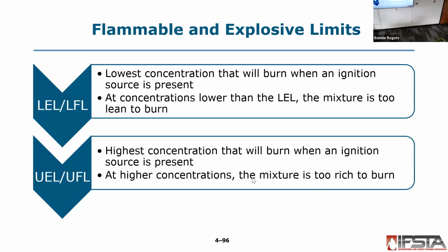All right, so we have our LEL and LFL, the lower explosive limit and the lower flammable limit. That's the lowest concentration at which it will burn. If the concentration is below the lower explosive or lower flammable limit, then it's too lean to burn.